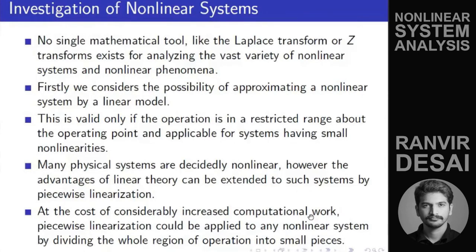The system that I may have studied, or for which I have designed a controller, may not work in real life. That you have to consider. And this is valid only if the operation is in a restricted range, like I said, about the operating point, and applicable for systems having small nonlinearities. This is generally the thing.